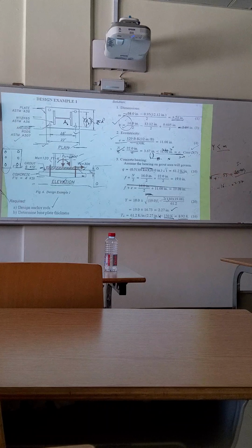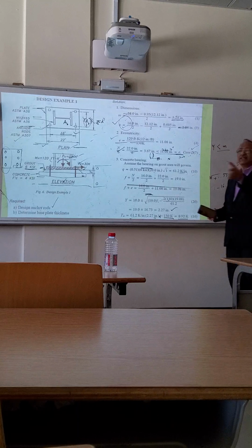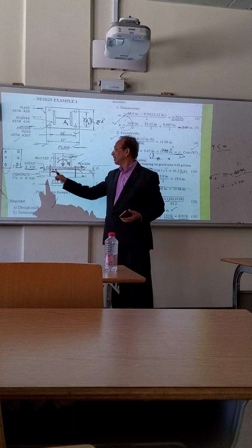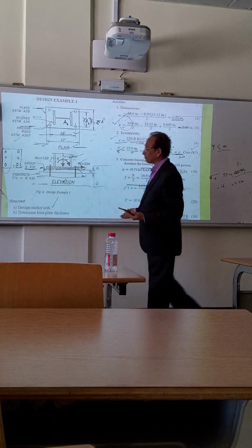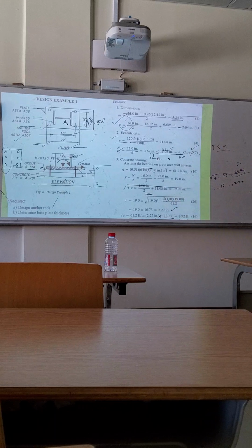In some cases, you may get only a small moment, or maybe there is no moment. Case A: in case A, there is no moment. So easily, there will be no chance of any tension. Only compression will be there, so you will check only for shearing. No tension.